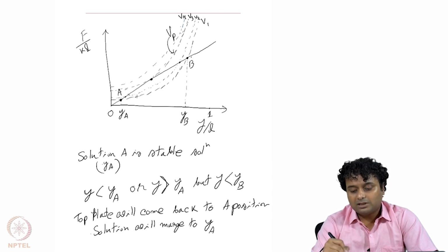It will reach a minima, and then start moving upward again, because after that the electrostatic force is increasing at a higher rate than the mechanical force. Accordingly, it will reach the B point where both forces are the same, and after that the electrostatic force will always be higher than the mechanical force.